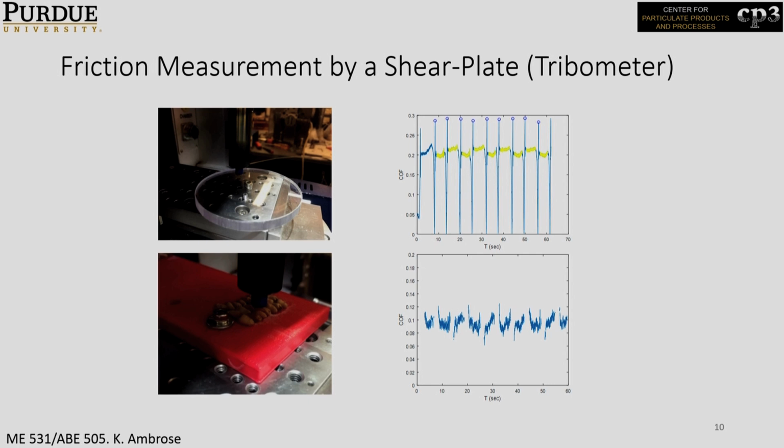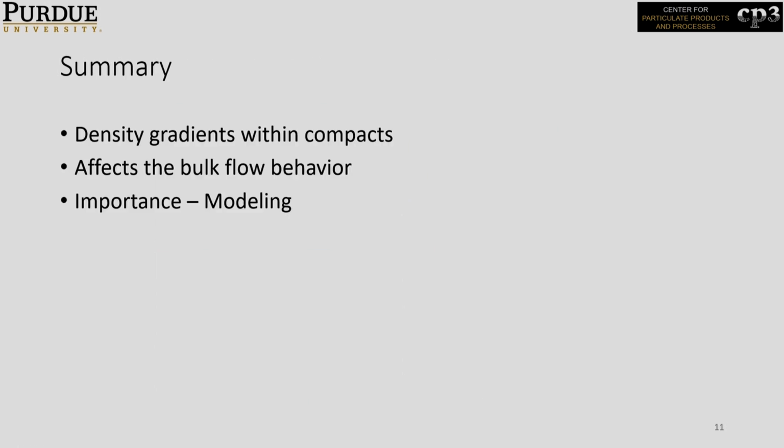We use the same setup for friction measurements and also wear on surfaces, how much you lose when two surfaces come in contact, mainly from friction effects. So again, same setup, from the peak values you get the static friction, and then from the plateaued value, or the constant force, you get the dynamic coefficient of friction. Maybe the central lab facility may have a tribometer here.